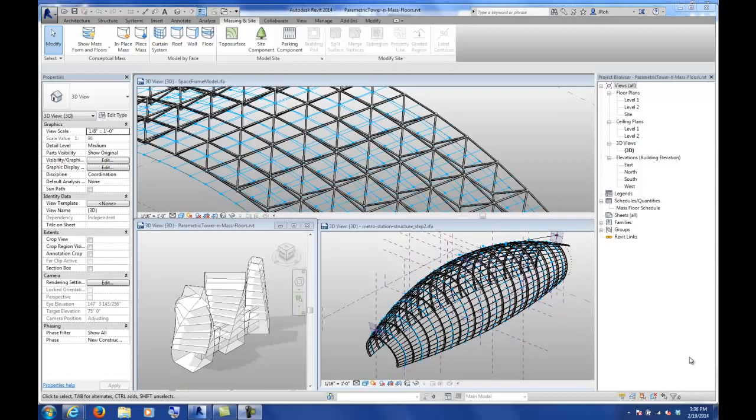And then I just want to touch base. We won't necessarily make all of those things that you see up there, but I want to touch base on how you could work with a curtain panel pattern-based family, which is a repeated element that you can apply across a mass. You can divide a mass into various configurations and then make one component and make it array across the whole surface. And as you move the mass, this particular form is always going to move with it.